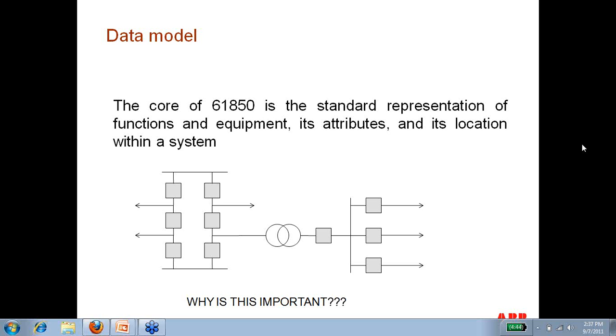So these were things that, once the 61850-9-2 was published, left a lot of details open to interpretation, which made it very hard for manufacturers to come out with a design that would guarantee that whatever we were working on would match what other manufacturers were working on. That became quite evident, and this is actually an issue that UCA took a leadership role on, and they released what's called the 61850 implementation guide, which in turn is being referred to as 61850-9-2 LE.